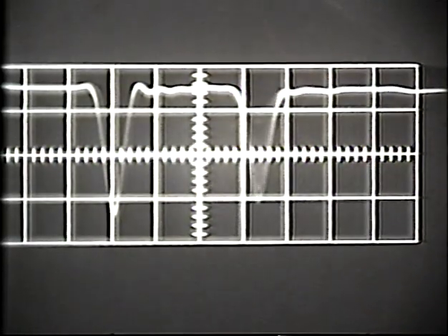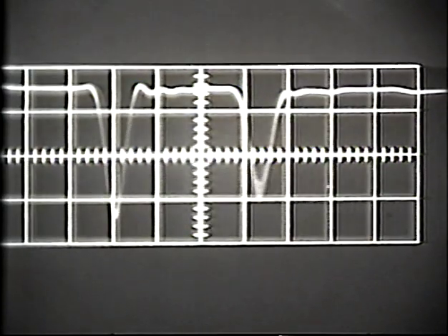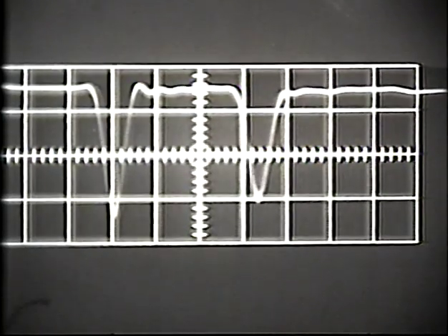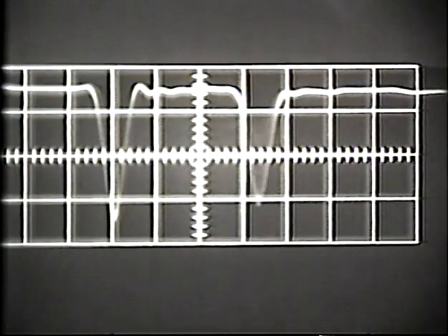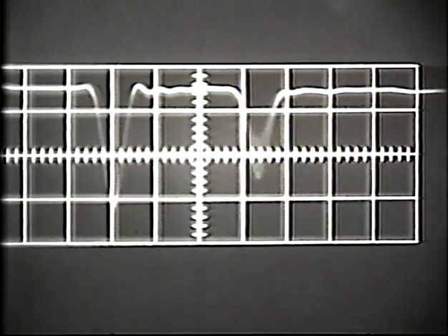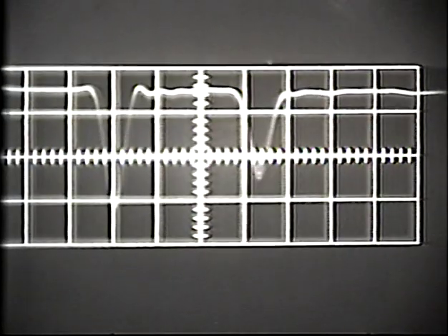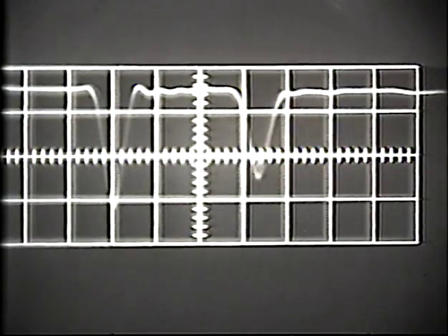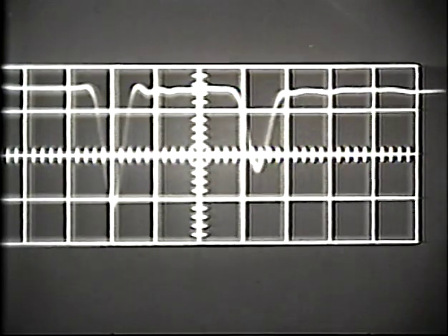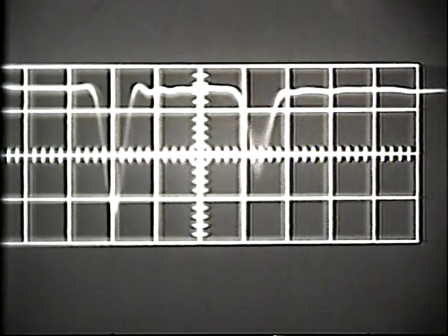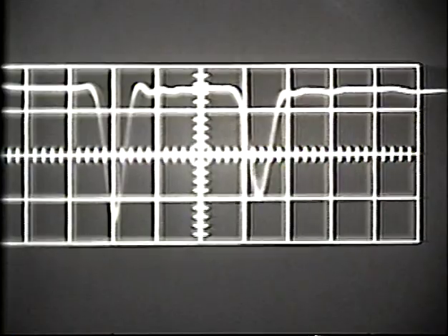So, from the distance on the scope face between these two signals, we can calculate the time of flight and thus the speed. Let's do it. The separation, counting from the left-hand signal, is 1, 2, 3 large divisions, and 2/10, 3/10 of another. That is 3.3 divisions, a separation of 3.3 divisions.